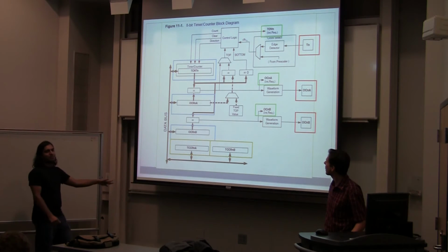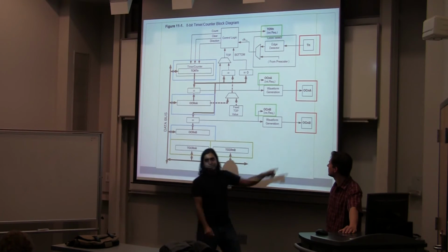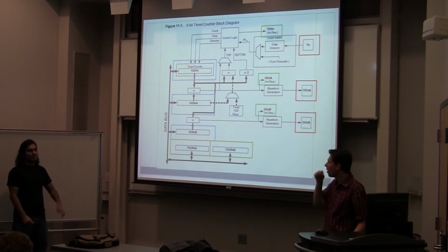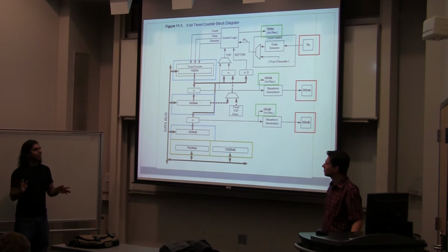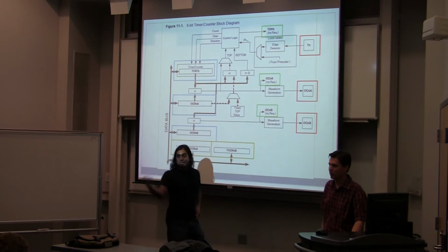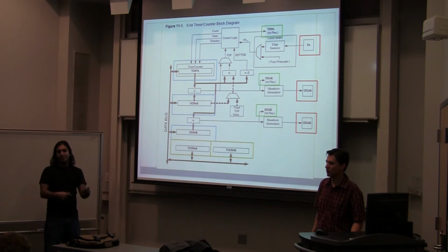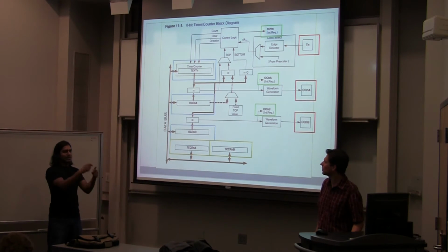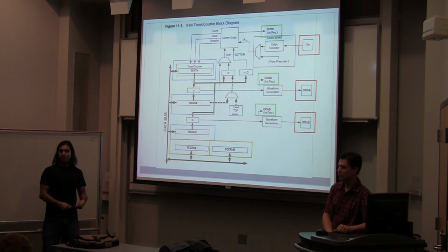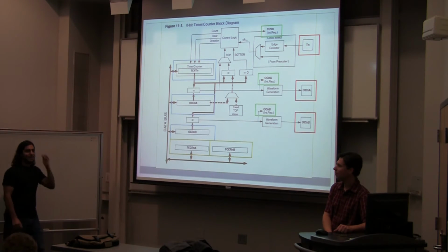And the difference between hardware PWM and software PWM is really just that if you have this directly connected to one of these pins, you just don't have to touch it. It's just doing its thing, producing some waveform, driving your motors, and you never look at it again. If you have it going to one of these ISRs, these interrupt service routines that you wrote, now every time this thing goes off, you're doing something, and so you have to keep track of what you're doing. That's the software part: it takes some time in your code for you to turn this bit on and load a value, versus not having to do anything and care about it at all.